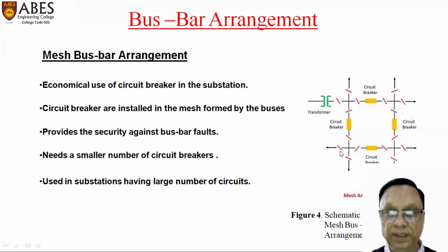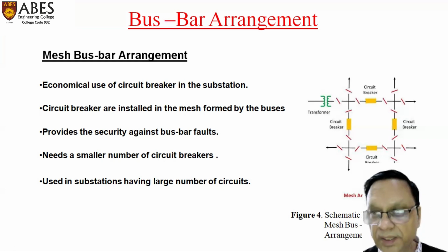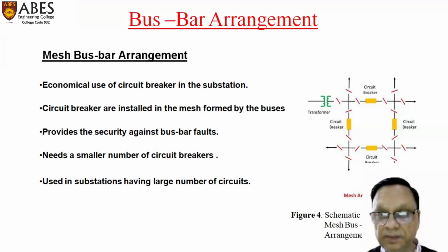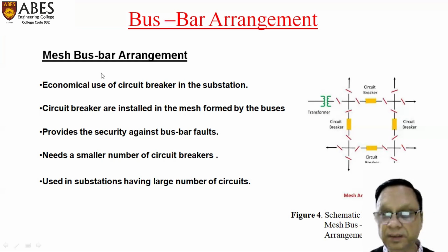It provides security against bus bar faults, needs a smaller number of circuit breakers, and is used in substations having a large number of circuits. It is widely used in substations where a very large amount of power is to be transmitted and the load is also very large. Suppose you are considering a distribution substation of any part of the city, then the load is very large. So there they are using mesh bus bar arrangement.